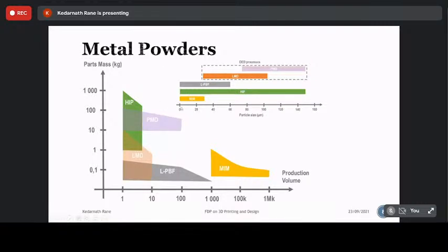We have a very specific powder particle size, even though it says that around 30 micron is possible, but it is a range of powder. I must recommend that 0 to 20 micron is the best powder particle size for metal injection molding and powder injection molding. When it comes to metal, you can get this powder particle size easily. But when it comes to the powder manufacturing process for ceramic, even a 20 micron particle size is difficult.